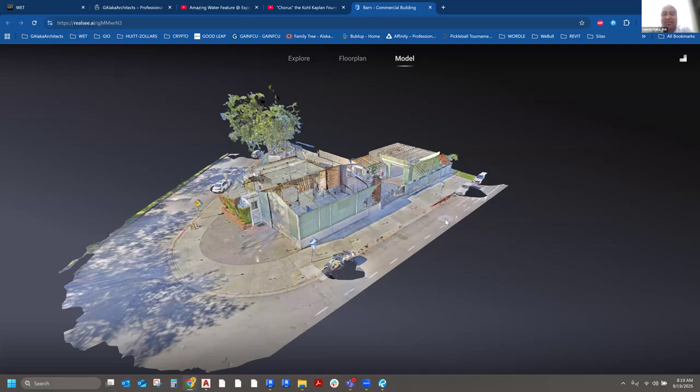So what they would do is they would send someone over to the site, and someone needs to sit down and measure all the walls, the doors, the windows, and then essentially go back into it could be AutoCAD, it could be ArchiCAD, it can be Revit, whatever it is, and someone's got to sit there and draw walls, windows, doors, curbs, all that kind of stuff to then give an architect a starting point of a drawing that shows here is your house. So that's why it's called as-built, because it's showing the existing conditions.